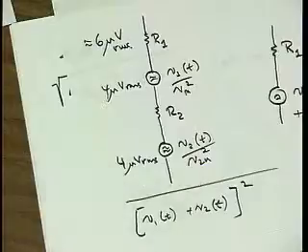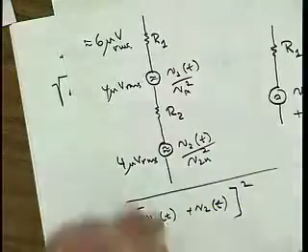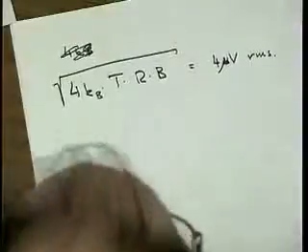So we have to be very, very careful. Noise powers add, instantaneous noise voltages add, but RMS noise voltages don't add. This is the most common mistake made with noise. And it's totally wrong if you make that mistake, and the IC is not going to work if you make that mistake. Okay? So try to remember this one.